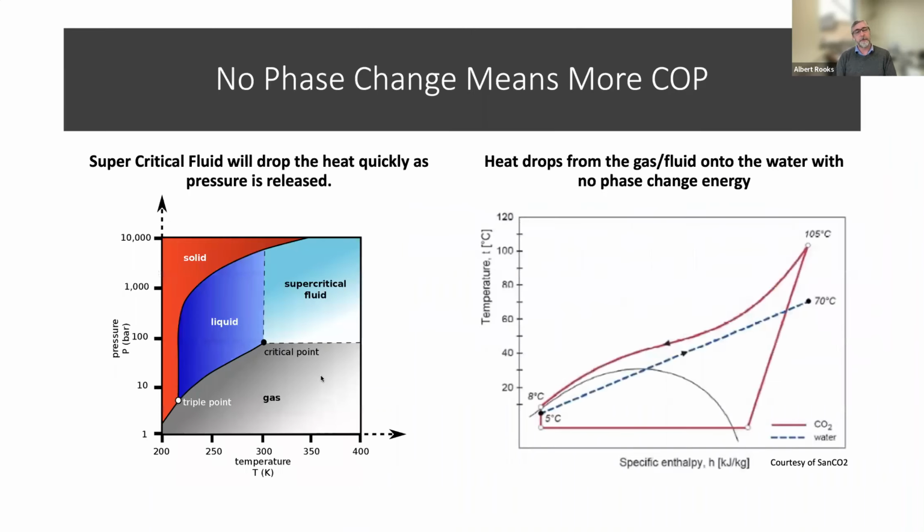And it's basically the difference with CO2 is it has all those refrigerant properties, and it goes through a refrigerant cycle where we'd normally go from a liquid to a gas and back to a liquid, that phase change. But CO2 is a little different in that when it is placed under a lot of pressure, over 1400 PSI, it gets very hot. And in those conditions where it's both under high pressure and very hot, it takes on a supercritical state or a transcritical state.